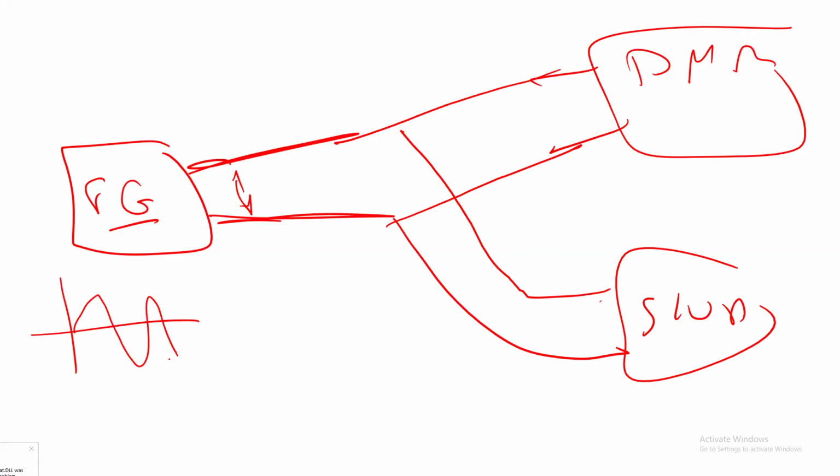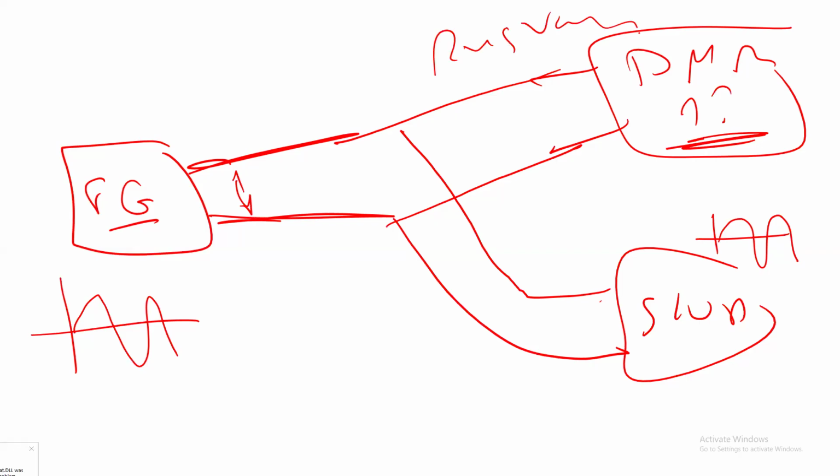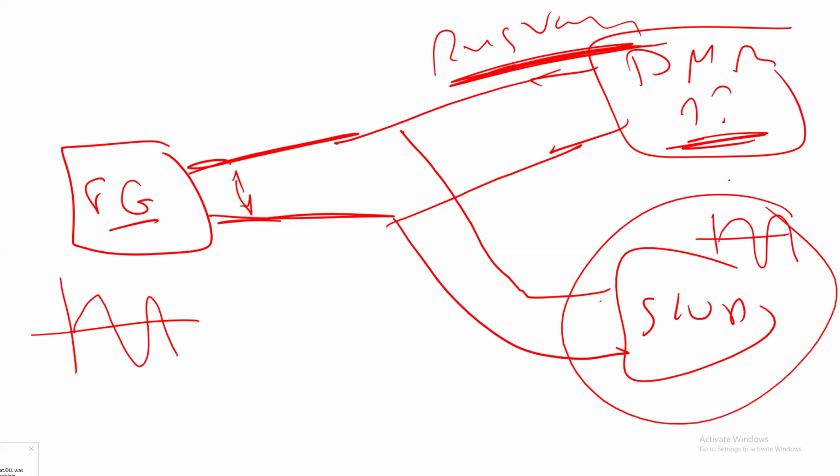Let me tell you something. If I generate a signal like this one, on the scope I have to see the signal this way. But the interesting part is what number you will see on the DMM. Actually, and this you need to learn, the DMM will give you the RMS value. Let me make it easy. If you use the scope, you will see the signal. You will see everything: the time, the peak value, everything.